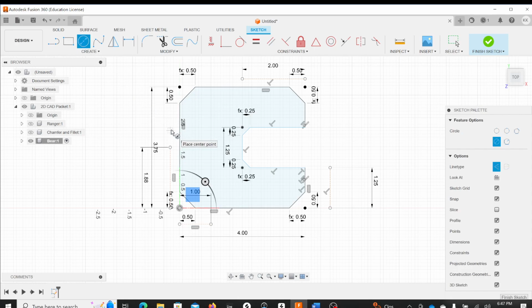So watch how I do this. I'm going to grab the circle tool, and I'm going to hover over this point. So when I come out here, see how it draws this dotted line? I'm going to kind of ignore that dotted line for now because it will come back. It knows that I referenced from that previous point.